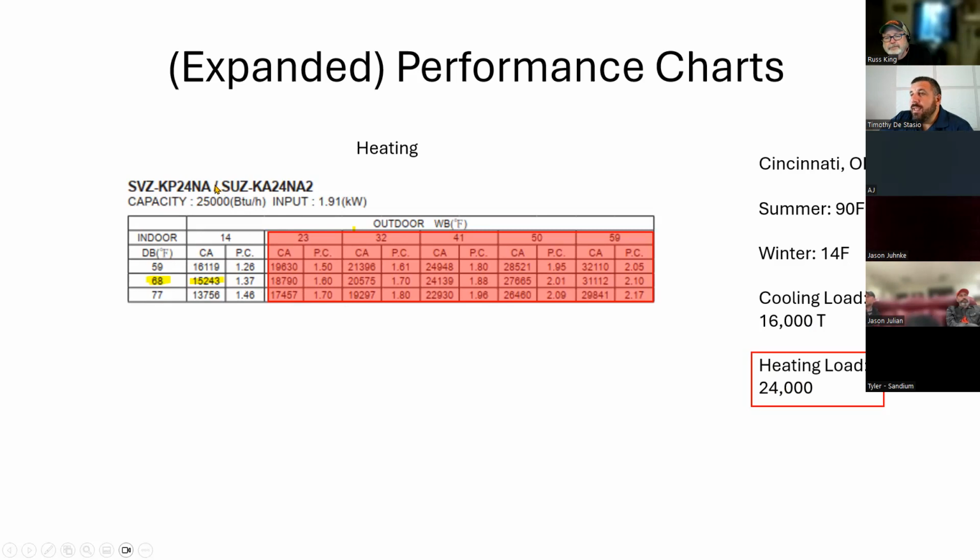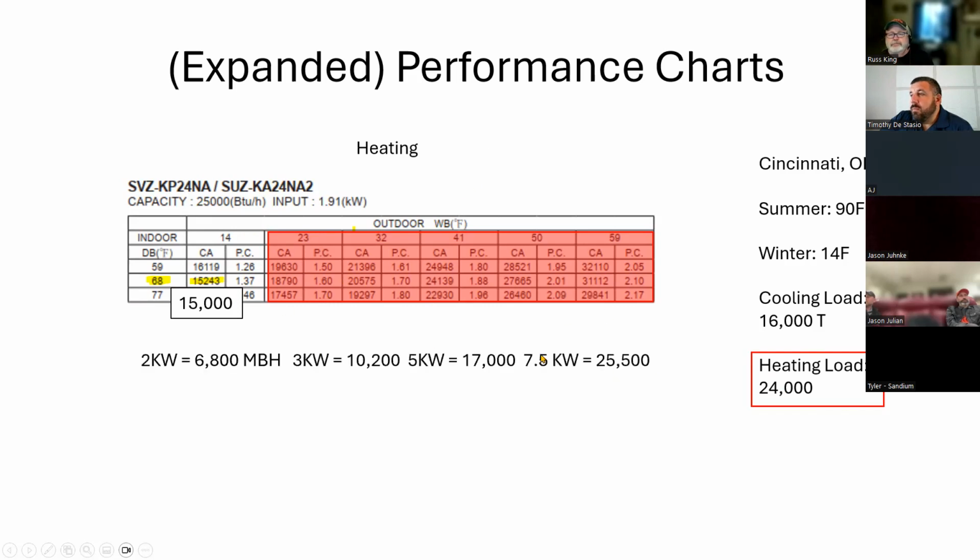And the reason why is this is not a cold climate heat pump. So it does not perform very well at 14 degrees. You would need the hyperheat for this. So again, making sure this is a variable speed heat pump, but it's not a cold climate heat pump. There is a difference. That's the lesson I'm trying to teach here, is that we would need a bunch of strip heat. And if we ripped out a furnace and we put in this heat pump, and even though it's only 3 kWs of strip heat, our client may not be very happy with us.